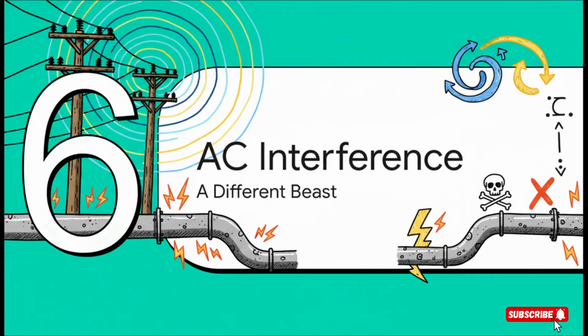Now, everything we've talked about so far has been DC current, but there's another threat out there, AC interference. This is a whole different animal. It usually comes from running a pipeline in the same corridor as high-voltage AC power lines, and it brings a double threat, a serious safety hazard for personnel, and a unique type of corrosion.